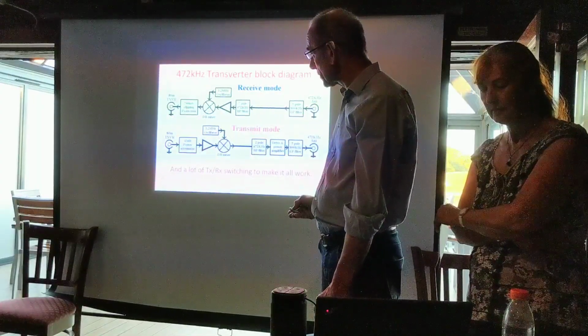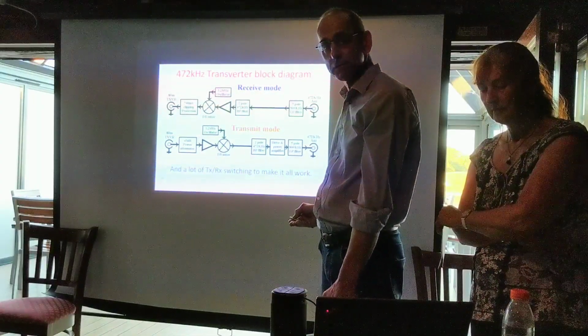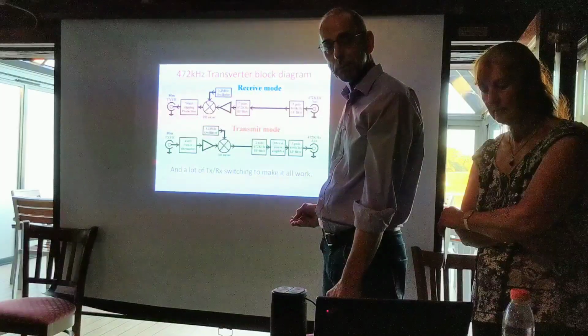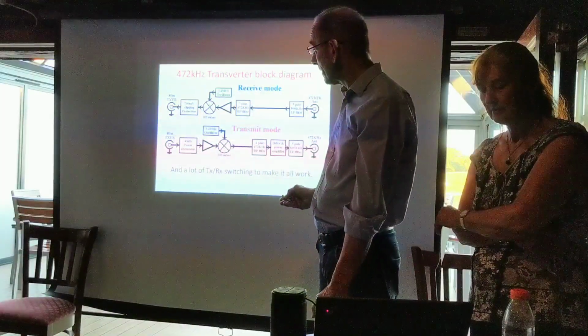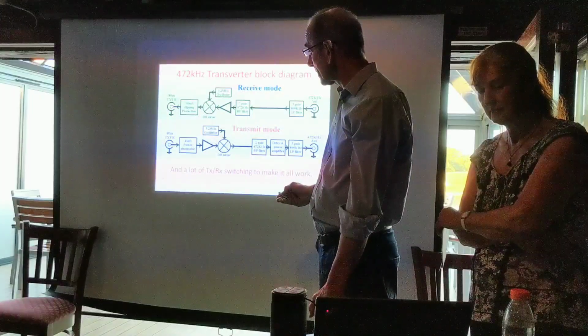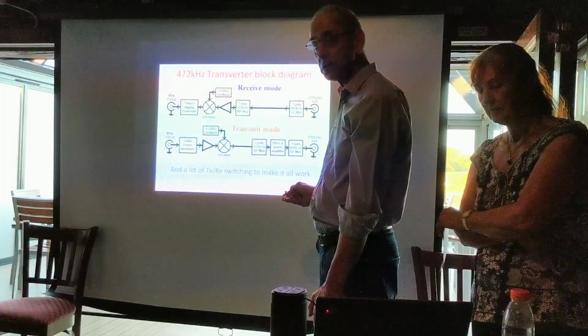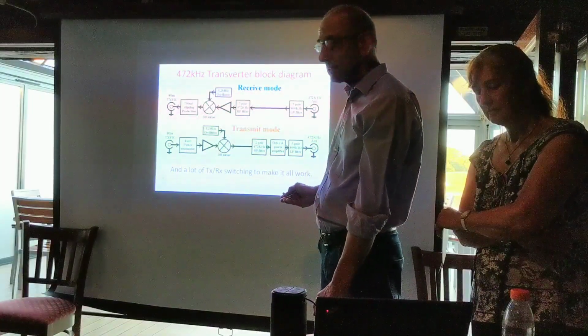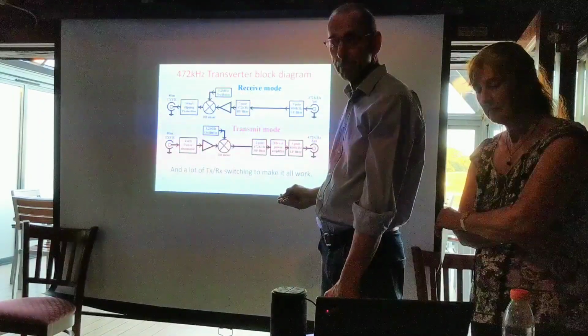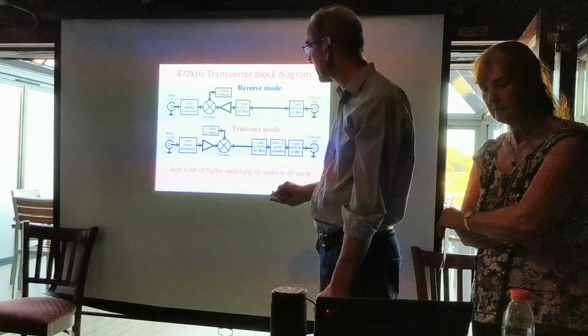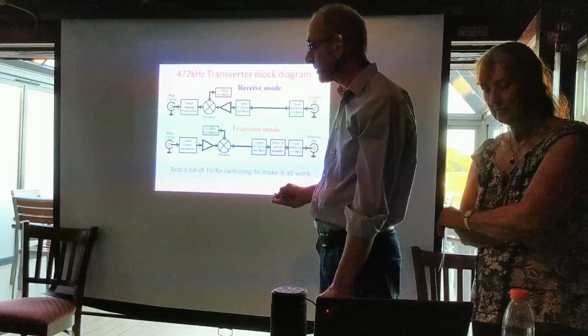Well, when you transmit, there's a slight time difference between the transmitted signal appearing and all that switching circuit switching it all over. And while that's happening, the transmitted output is potentially connected to this mixer. So you really want some way of making sure it doesn't blow the mixer up while that little switching process takes place. So we've got a little clip protection circuit in there.